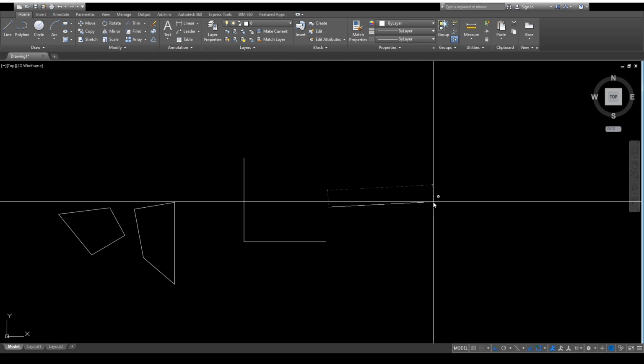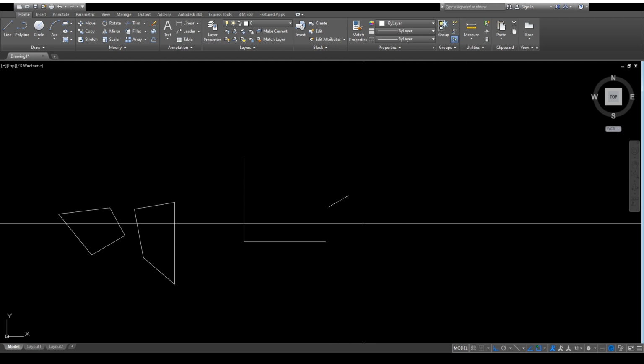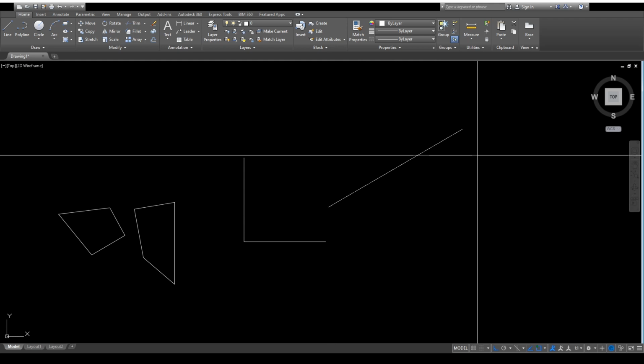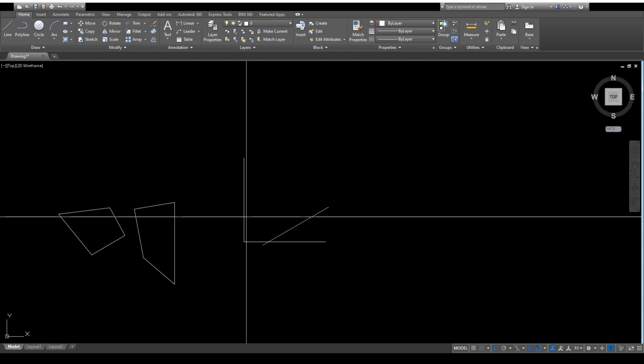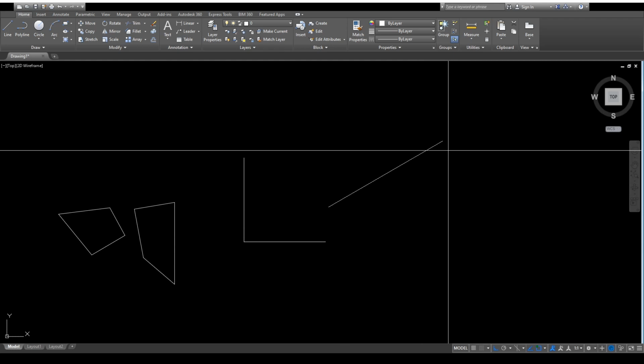So, sabi ko kanina gusto kong mag-drawing ng 30-degree line. Ang sinasabi ko is shift, angle, and then I type 30. Ibig sabihin, 30 degrees yung angle na gusto kong i-drawing na linya. When I press spacebar, ayan, automatic na ang ido-drawing ng AutoCAD is a 30-degree line. Pwedeng pa-upper right, pa-lower left, pero you can rest assured na 30 degrees yan from the horizontal.